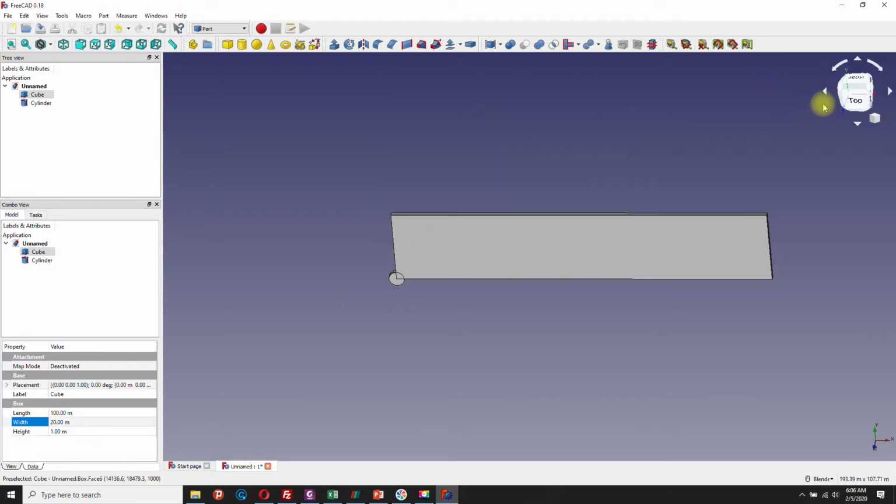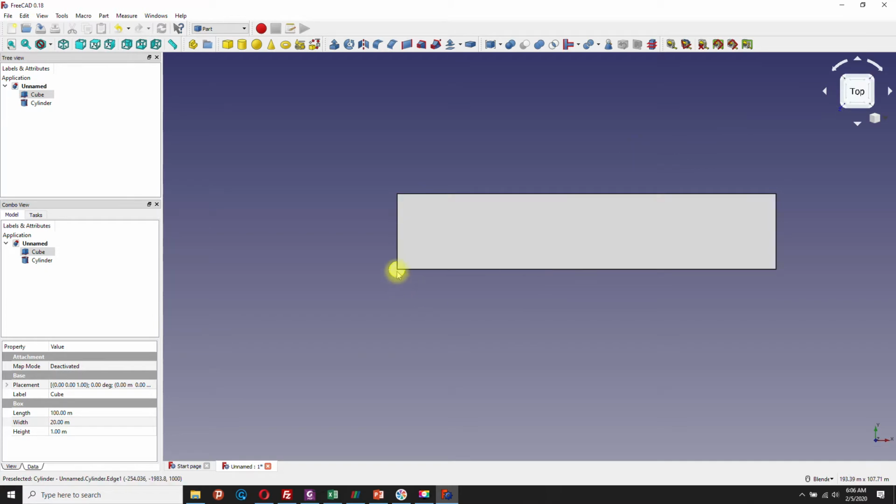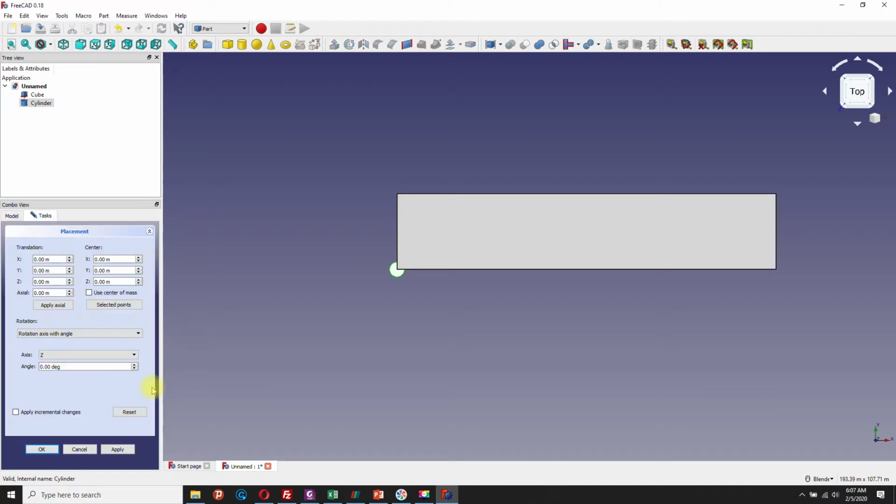So as we can see here now, the cylinder is located somewhere there, which means we must transform it 20 meters in the x direction and 20 meters in the y direction, so that it resides somewhere there. So we take the cylinder and then we click there to adjust the location of this cylinder. Let's say, okay, I put it there 20, and then I put another 20.